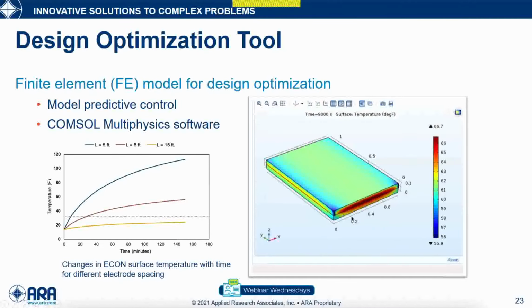So this is the slab, with 2 electrodes connected to the power supply, and this is just an example plot between the temperature and the time. For example, if you have an ambient temperature below freezing point, about 10 Fahrenheit, how long is it going to take you to reach about freezing point? The reason we need to reach above the freezing point is in order to melt ice and snow.